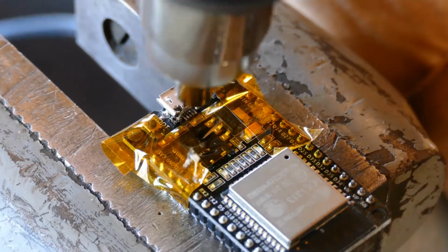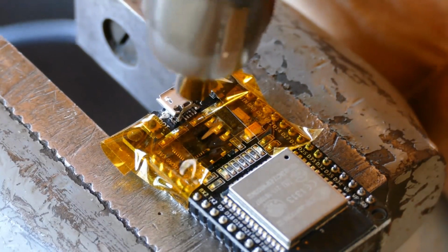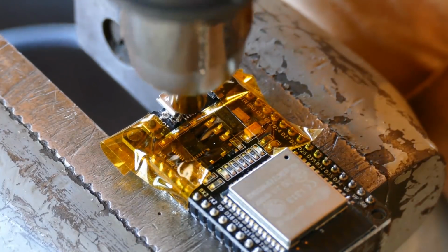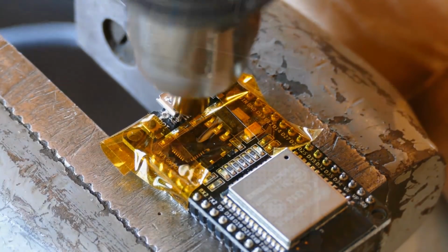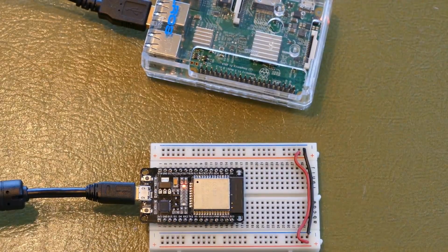Okay, the solder's melting. Looks like I got one solder bridge on the data pins. Nothing that a little solder braid can't fix. I'll need some more practice with the hot air gun, but the jack looks good enough. Back on the breadboard, I'll plug in the USB cable. Now it's got a tight fit and the LED power is on.